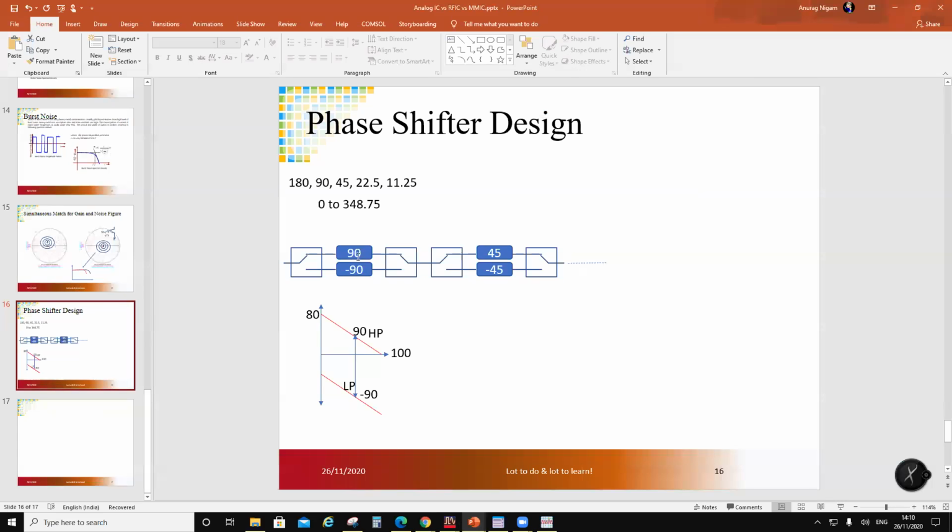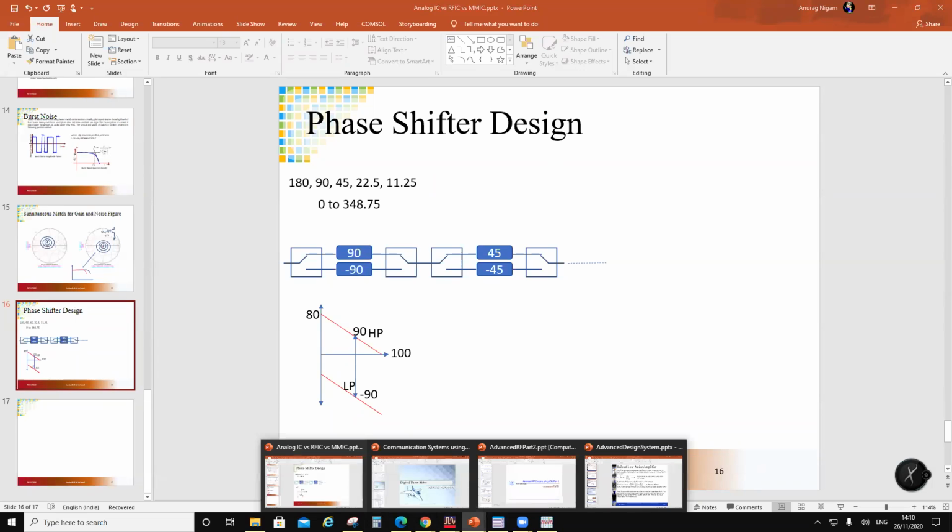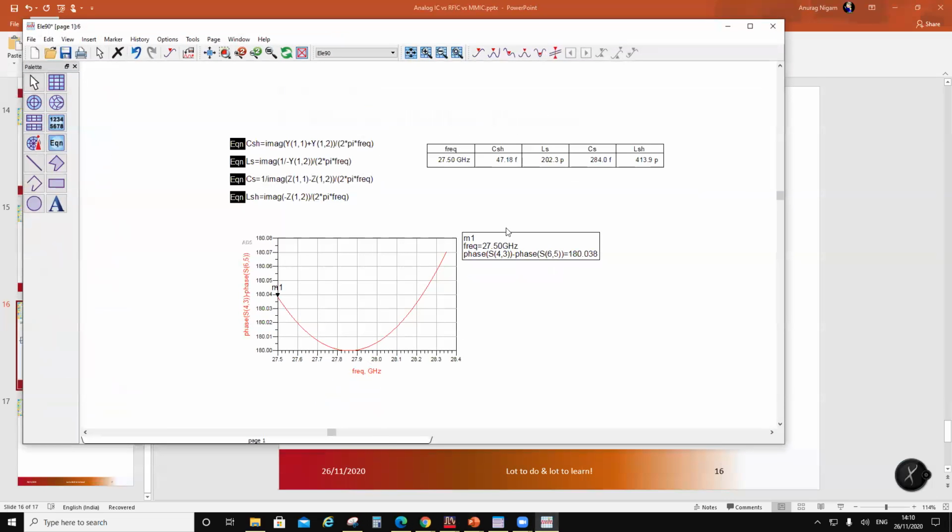How do you generate a phase advance of 90? You have to make one network high pass and the other low pass. If you just use transmission lines, then both are low pass. So if both are low pass, what would be the difference? Basically, you will not achieve the bandwidth if you just use transmission lines, because both are going to be low pass elements. And then the difference you guarantee is 180, so this additional 180 will not be broadband.